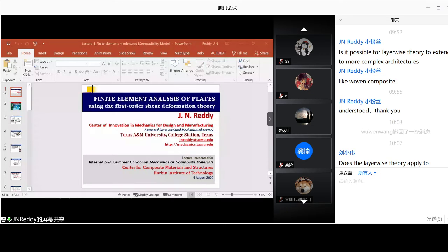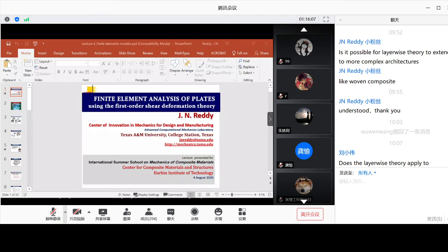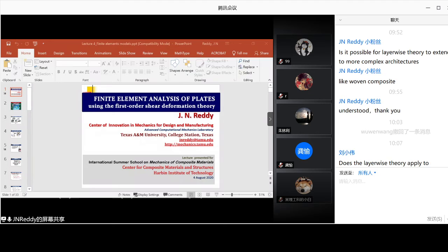Every component of displacement has its dual variable. An axial displacement has the axial force. A transverse displacement has a transverse force. So you will have this duality. And the algebraic relations are between the nodal values of displacements related to their dual variables at the same nodes. So that is the end product that we get out of the finite element model development.